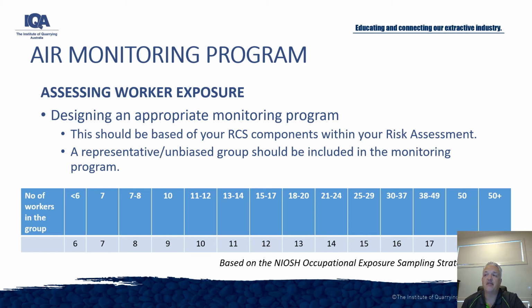Once a baseline has been established and has been statistically assessed, these numbers can be reduced depending on the concentrations identified. Where monitoring programs are developed in accordance with legislation requirement, approval must be sought before changing any of the numbers down. Increasing the numbers isn't an issue, but if you decrease them, you need approval before you can actually do that.